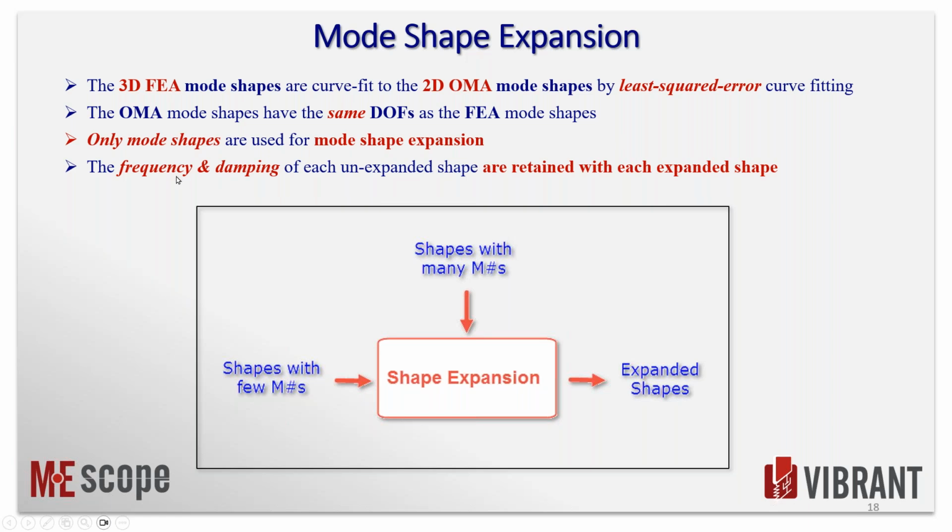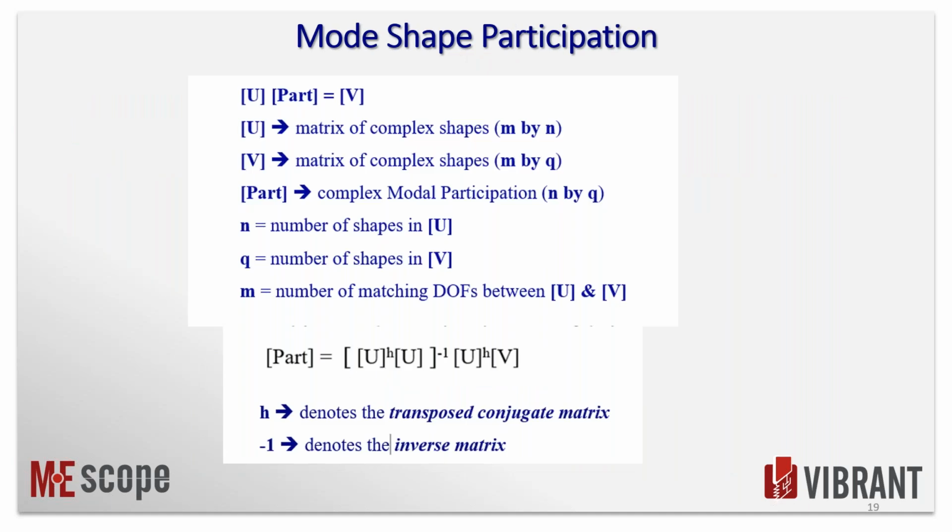It's just the mode shapes themselves. And those are, in a sense, a reasonable deformation of the bearing blocks and the base plate of this machine sitting on a fixed foundation. So those are assumptions that you would make in any FEA model, unless you wanted to go ahead and model the whole tabletop and so forth.